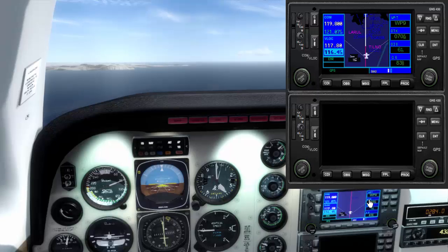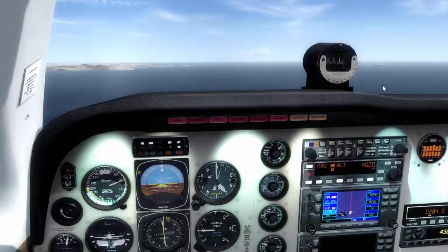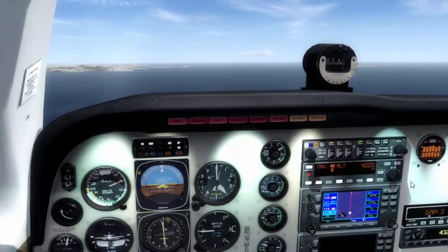and we can follow radials if we need that, okay? Observe that we have our speed very well configured, okay? We are flying exactly at 80 knots. We should fly at 76 knots, but well, we have 4 extra knots. That is nothing, okay? So yes, we are flying fine, okay? And we have range for the radial because you are listening to it, and very soon we will reach the first segment of our approach, and that is the initial approach fix, okay?